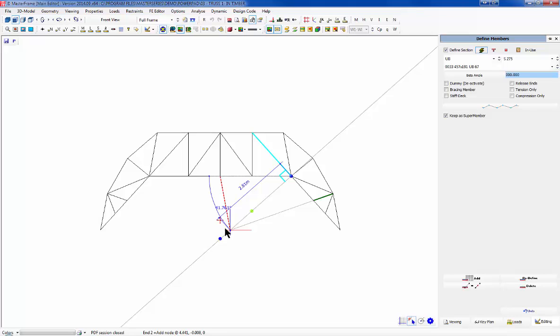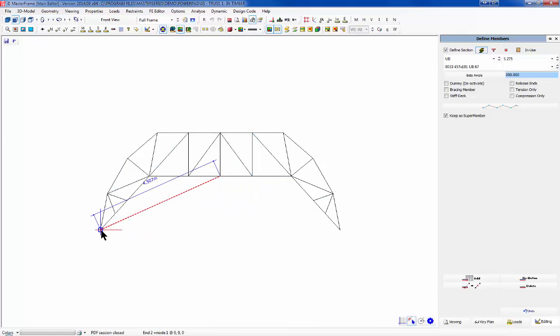In this example, I'm coming perpendicular to that cyan member and I'm coming as a projection from that dark green member. So we've got some really fancy automatic snapping for you. What I'm going to do is hover and grab that as a component, and then I'm just going to come straight down and put my member in. Now I was messing around there and I didn't quite get it right because of this little member here. I should have gone in and removed some more of my snap options. But those little pesky items are quite useful.